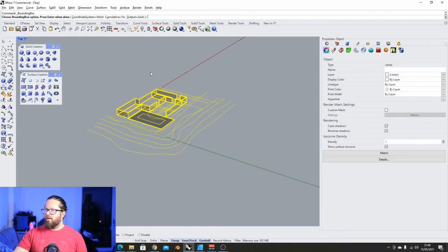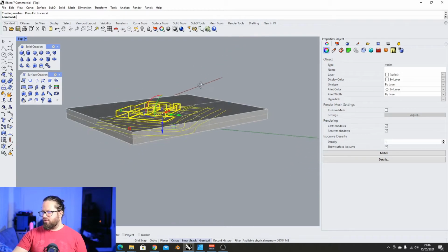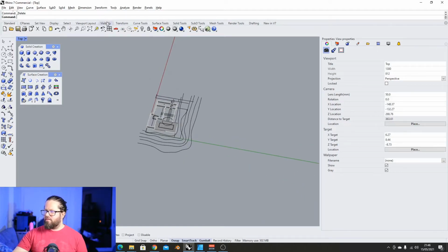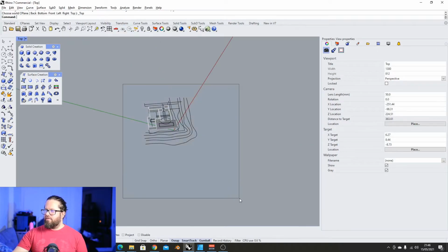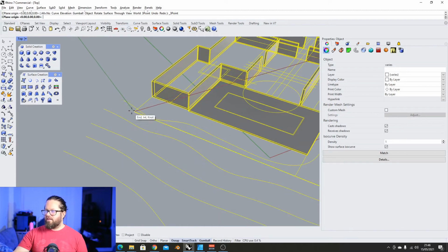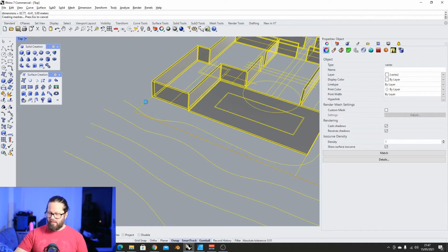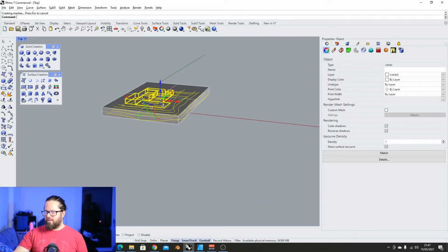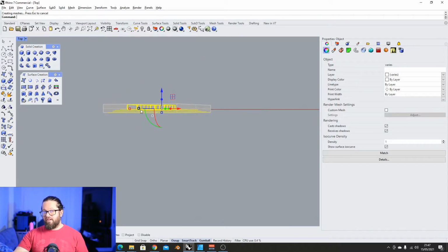Output solid. If I now press, then I just get one big box, and this is based on the world coordinate system. Now if I don't want that, then I could choose the construction plane. Okay, that means if I set the construction plane here, it kept actually, that's really good, because I was able to create the construction plane within the command, and then it finalized the command. That's something not a lot of software have.